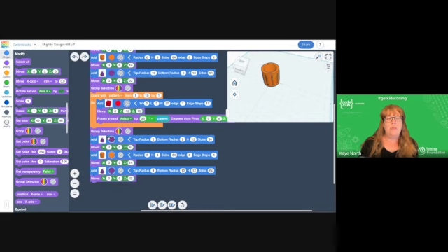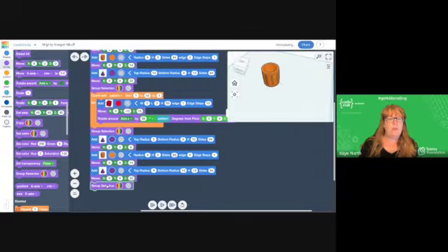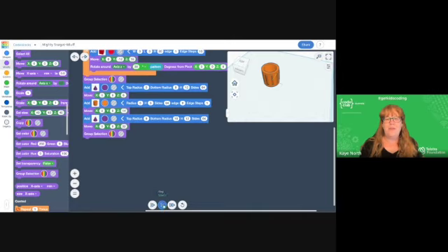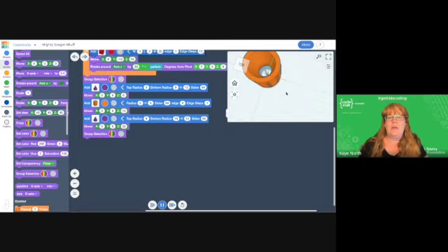Now, again, we want to group these 3 shapes together. So let's add in a group selection. If we run that program now, you are going to see it build the outside shape. It's going to go through those 10 iterations of putting in the outside little cutouts, and then we can watch it as it builds the inside cone, and we have got our inside piece of the fidget spinner. You can see it's just a little bit smaller than the hole on the inside.